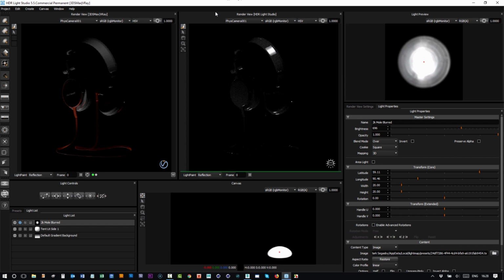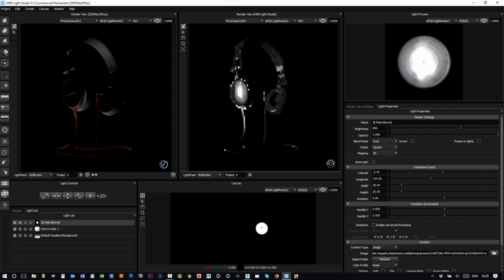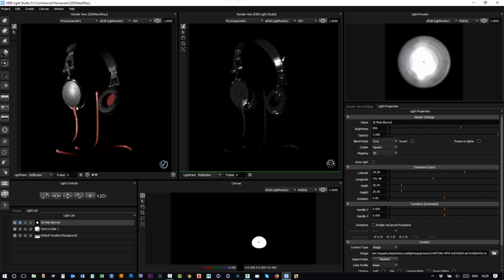So if you wanted, you wouldn't need to have this view open at all if you wanted to light your V-Ray shot. At the moment, we've of course got two renderers working at the same time. So in terms of freeing up some resources for V-Ray, closing this view could be great. One advantage of this view is that you do get this clicking and dragging and the instant feedback, so you can actually discover sweet spots for lighting simply by dragging over the surfaces.